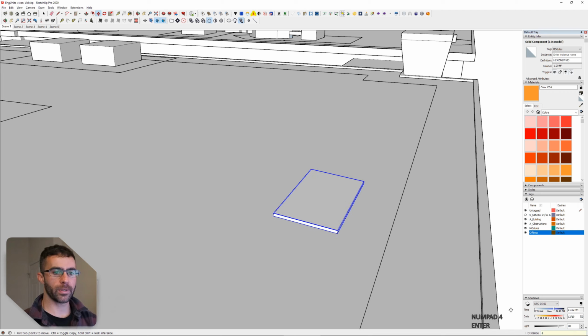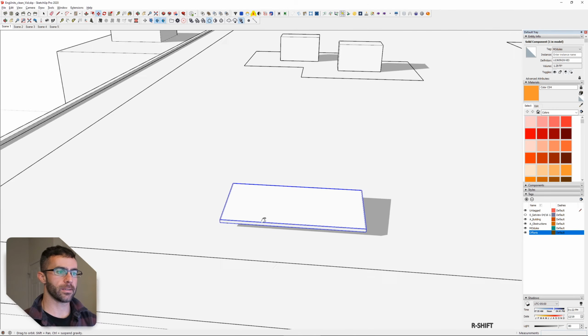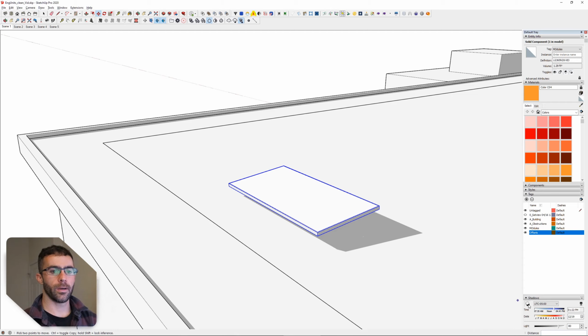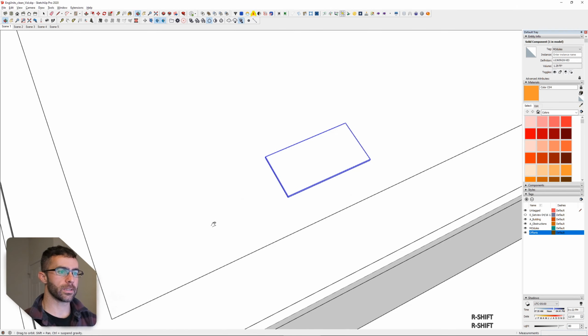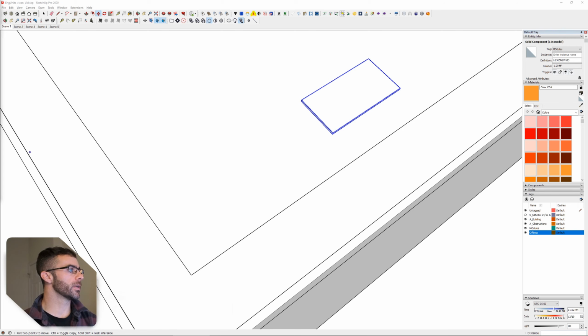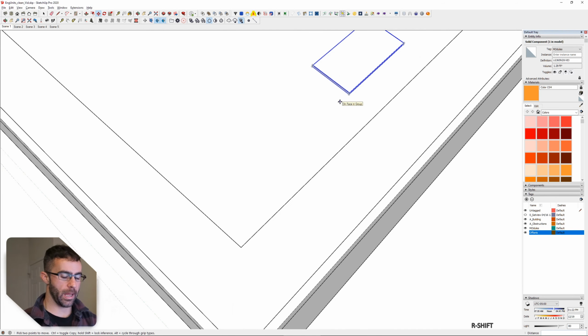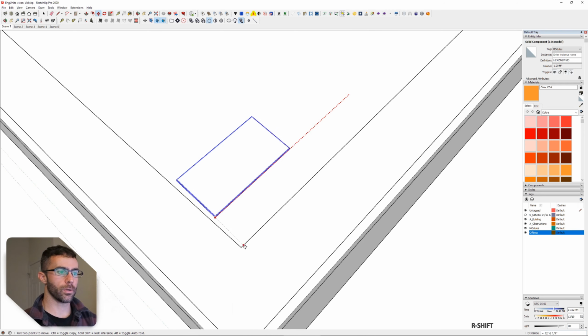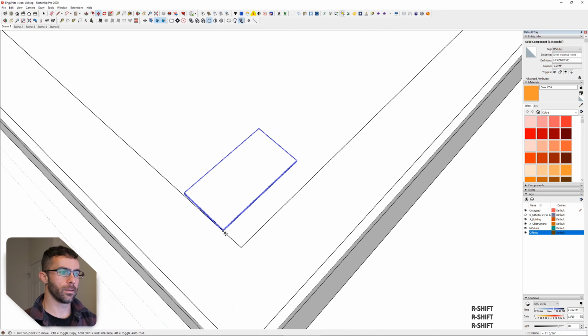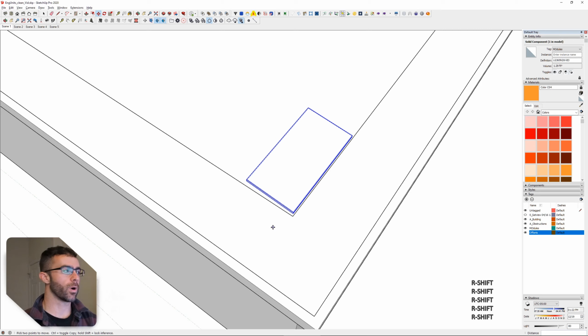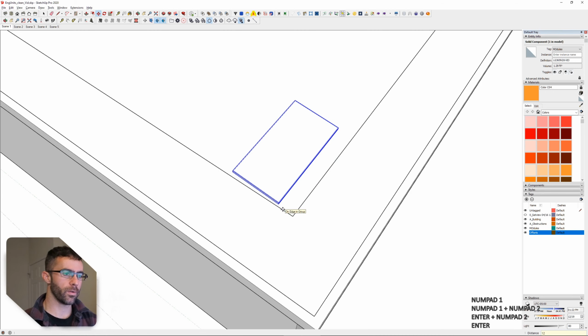So now if we turn on shadows, you can see that it's elevating above the roof. I'll turn off shadows for now, just to keep things speedy. The other consideration is how far away from the edge. We could drag this over exactly over our offset, but that doesn't account for the extra space required. Once again, you would need that dimension, or you can measure it off of the cut sheet, but it's a pretty safe assumption that if you're 12 inches in, that's got you covered because the inter-row spacing was 9.9.